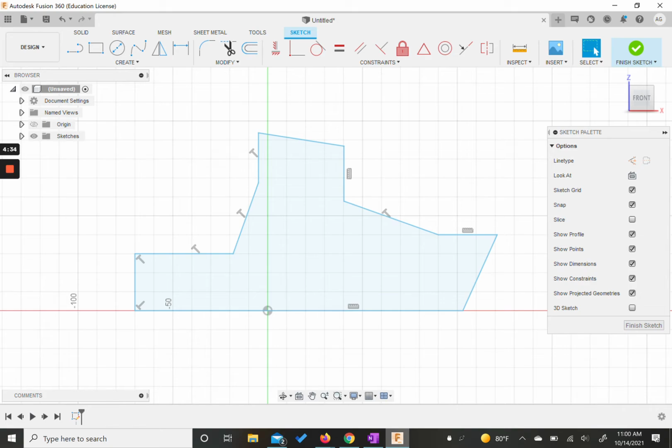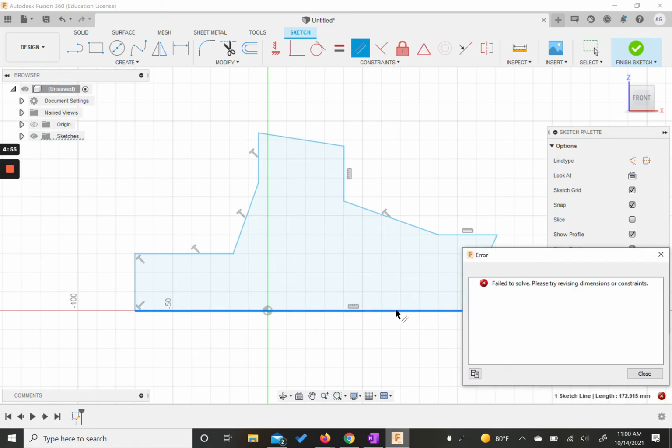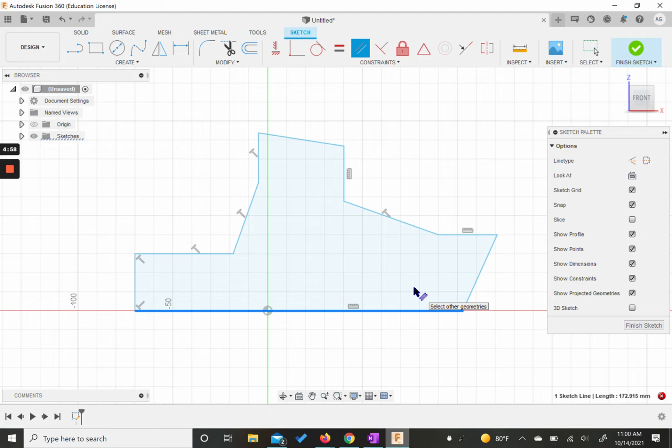First of all, it says that our line 1 and 9 should always remain parallel. We have these two horizontal constraints. Both are horizontal. We could take a look and see, but this should tell us that it's over constrained. Yes. So these are both horizontal. We already have that. Then we have our line 6 should be parallel to the x-axis. Our 6 would be this one. So what we can do is we have a couple options here.